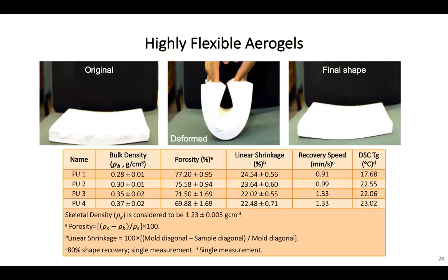So these are the fundamental material properties, including the density range and porosity that we got, with density as low as 0.28. We focused only on the samples that are structurally reliable. On the chemistry side, we can go to a lower density, but from the mechanical side, that sample is not suitable for us. So that's why we ended up with 0.28 gram per centimeter cubed.